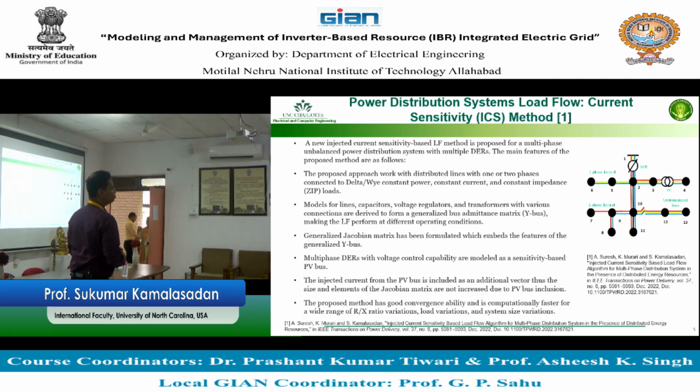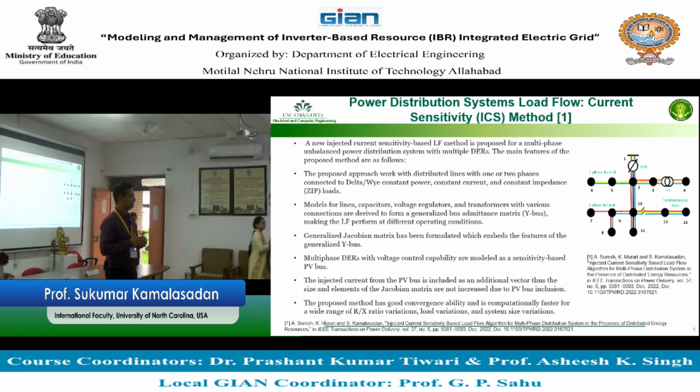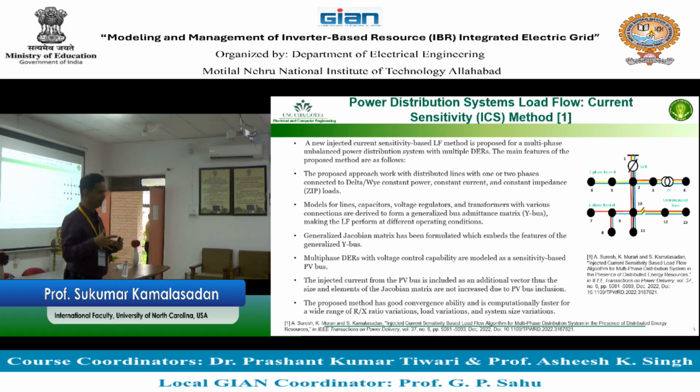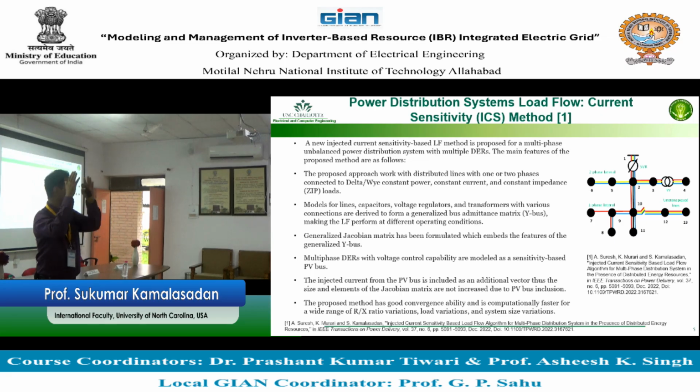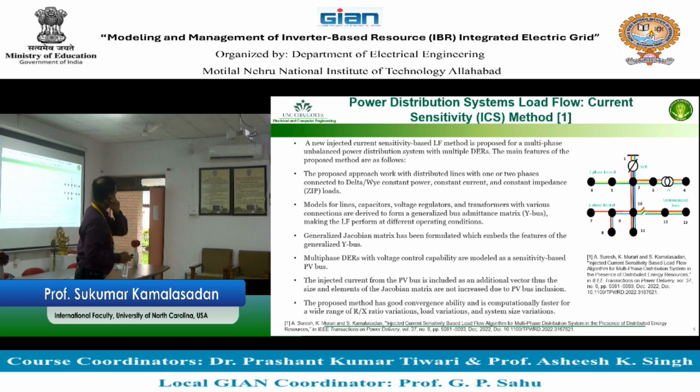Yeah? So having said that, this approach you can bring in. In the forward backward sweep, we don't do the sensitivity for the entire power grid. We only do the change in voltage drop in every system. So calculate the load, then remember, we calculate the voltage drop, then you calculate the voltage. That's how we do it. So first what I will do is show you this powerful algorithm compared with forward backward sweep. We just did it for about 5 minutes yesterday, so I'm just going to repeat that and then show you.